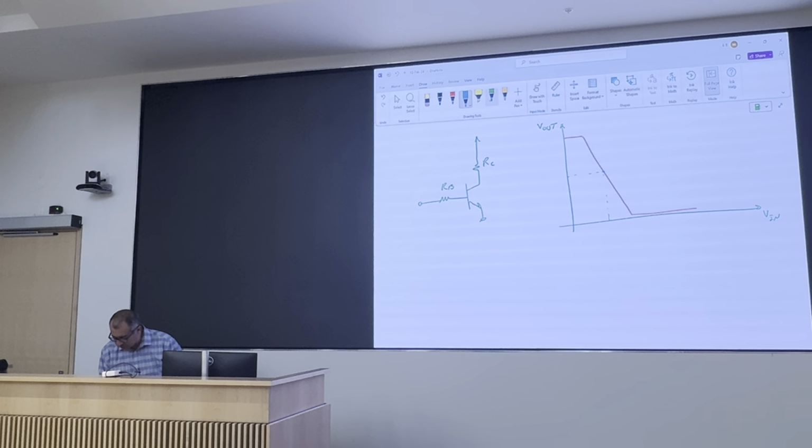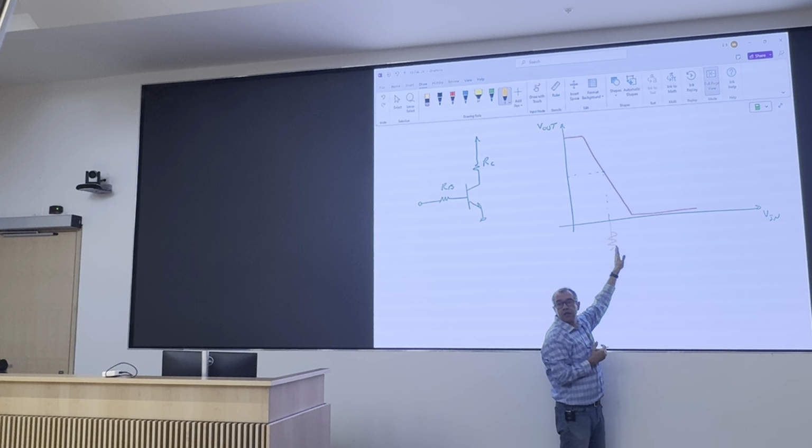It's changing around that bias point, right? So I'm not changing the operating region of the device. Let's say this is a Vin of 1 volt, this is 10 millivolts. So what do you mean by biasing? What exactly are you referring to? It's setting IC and VCE, so DC conditions.